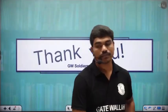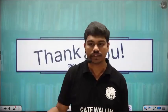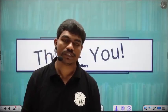We'll go for pumps in much more detail in the next class. Basically a pump uses the same formulas, but is like a reverse operation, where we supply the mechanical input and the fluid gains energy. Calculations and all, everything will remain the same, only some terminology like cavitation and net positive suction head will come up. In the first two classes and in today's class, whatever I have done is the basis for any turbo machine, like the gas turbine, steam turbine, it's the common idea. Depending on the type of fluid and machine, the assumptions and applications change, that's all. The rest of the parts are easy, no issue.